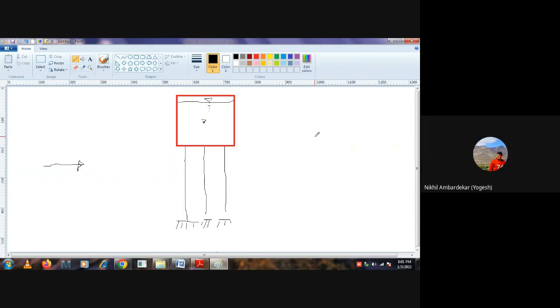If you apply any lateral force, our universal assumption is that the force will be applied to the CG of the structure. Right now I don't know where that CG is. It may be somewhere here, or here, or here. But do you agree that this force needs to be applied to the CG of this entire system?